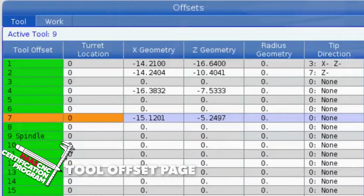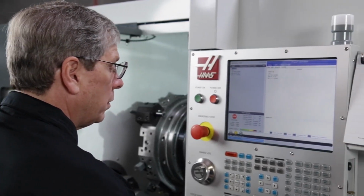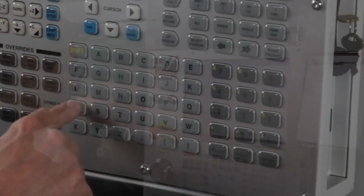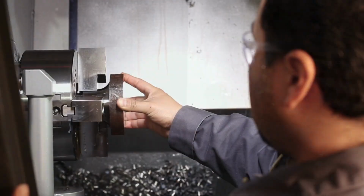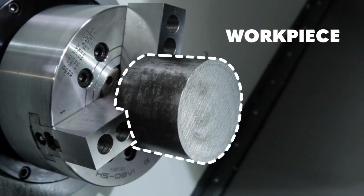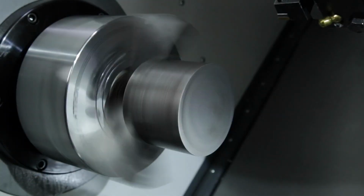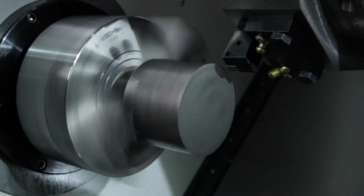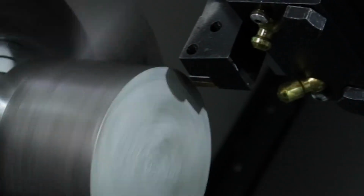Now, when you're starting out as an operator, your supervisor will be setting up the job and they will set the tool length offsets correctly. But we're going to show you the basics of how it's done so you have an understanding of the complete process. I have my workpiece clamped in the chuck. I command the spindle to rotate at 500 or 1000 RPM, and I jog my first cutting tool, tool number 1, close to the part.